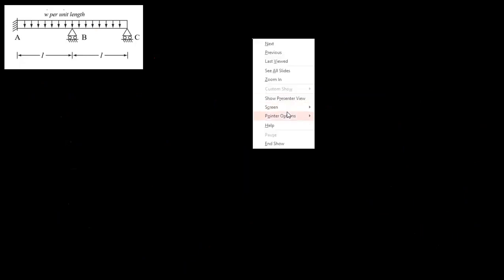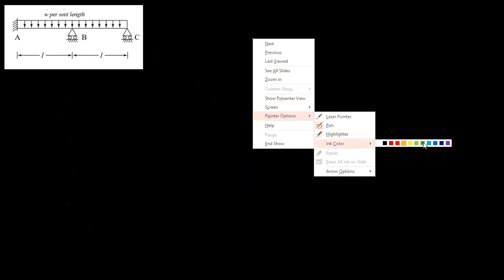So you can see this, it's a fixed support and with two rollers, right? So there you have one reaction. It does not have any horizontal loading, so probably I don't have any horizontal reaction, right? So it will only have a moment here, and a vertical reaction and another vertical reaction. So together you have four unknowns. But how many equations do you have? You have only two, right?